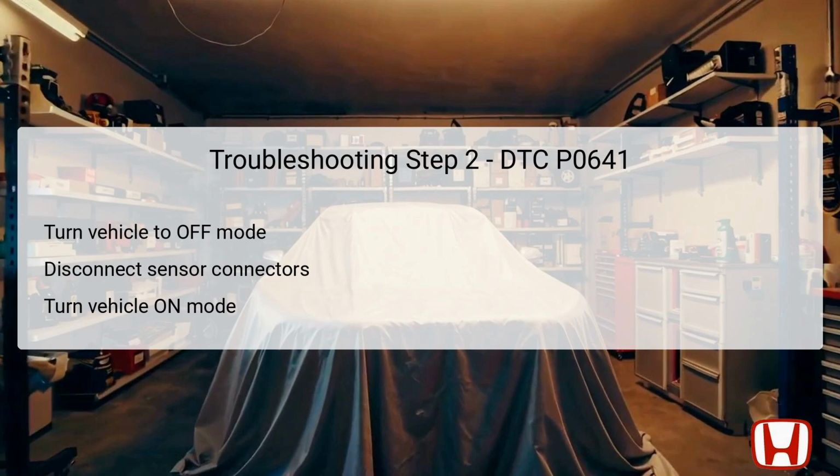After disconnecting, turn the vehicle back to the on mode. This will allow the ECU to run diagnostics without the input from the disconnected sensors. Once again, utilize the HDS to clear and check for DTCs.